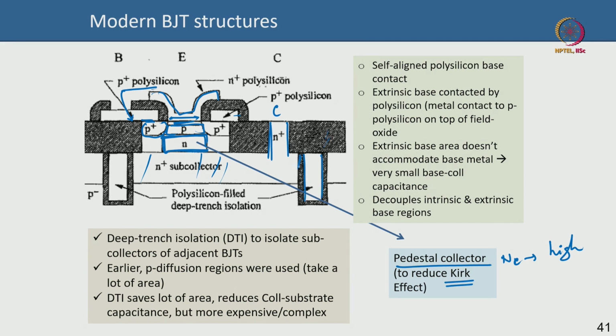This oxide can surround the deep trench filled with polysilicon. This is called deep trench isolation, to isolate devices or even entire blocks of circuits. This is your shallow trench isolation. This is your field oxide. This is your field oxide. This separates the base and the collector.